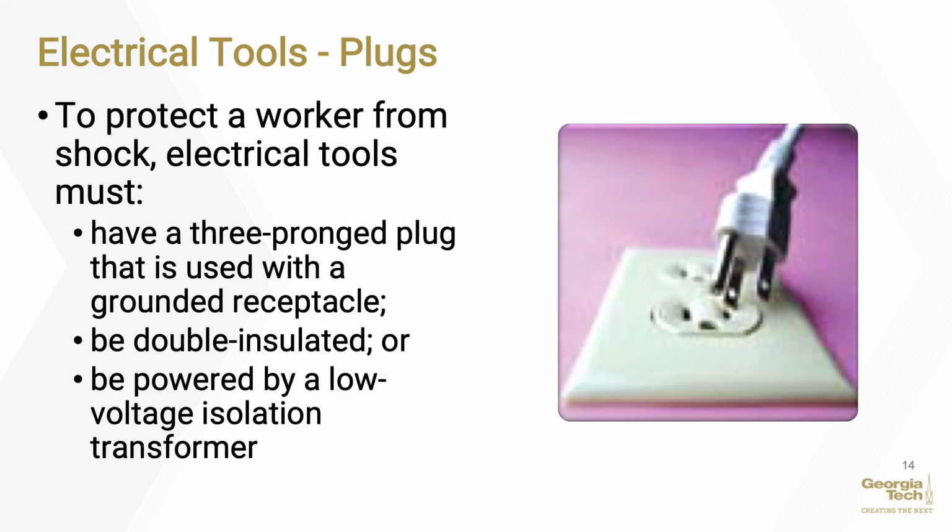Grounding a tool or electrical system means intentionally creating a low-resistance path that connects to the earth. This prevents the buildup of voltages that could cause an electrical accident. Grounding is normally a secondary protective measure to protect against electric shock. It does not guarantee that you won't get a shock or be injured or killed by an electrical current. It will, however, substantially reduce the risk.